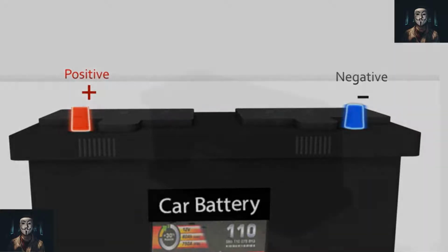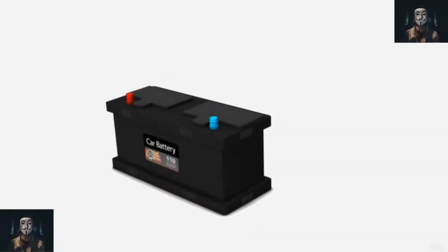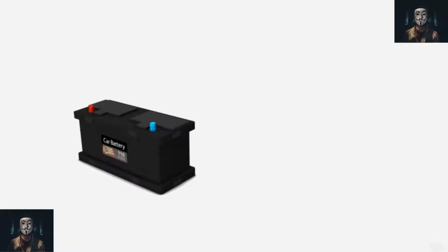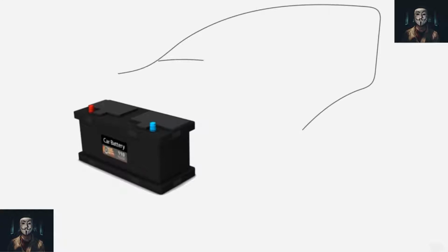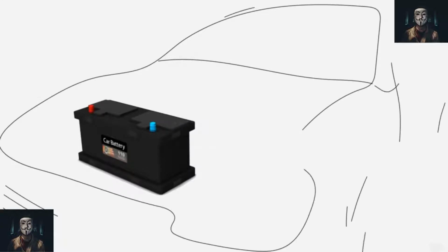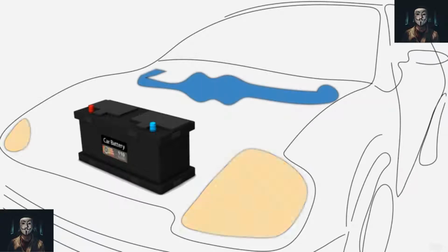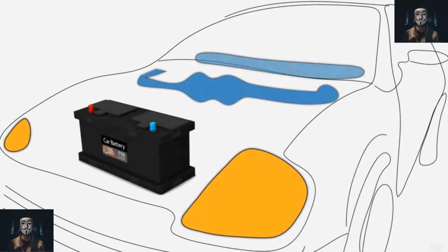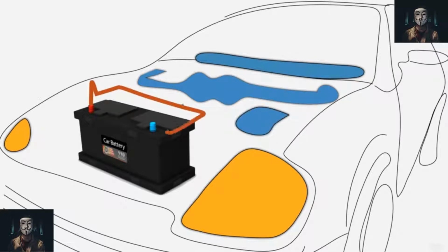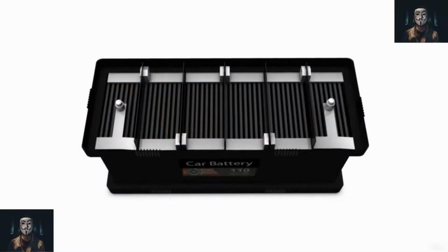Batteries. A good supply of electric power is necessary for modern vehicles. The engines require a large current to operate the starter motor, and many other systems are electrically powered. All modern cars use a 12-volt system. The majority of vehicle batteries are of conventional design, using lead plates in a dilute sulfuric acid electrolyte. These features lead to the common description of lead-acid batteries.